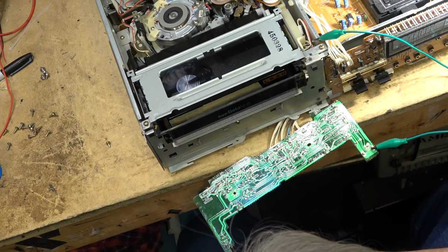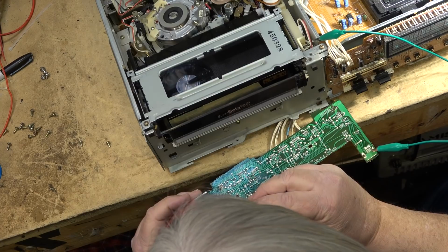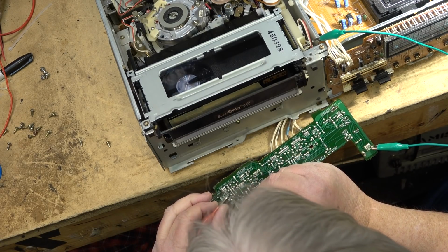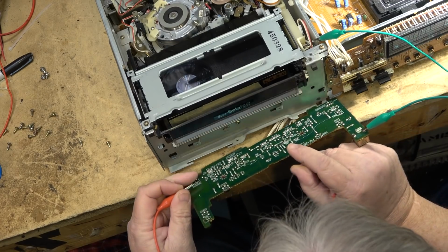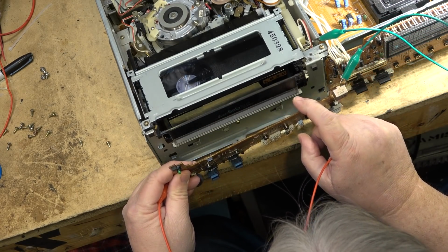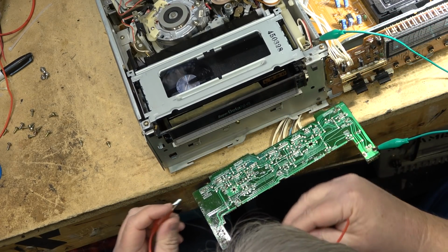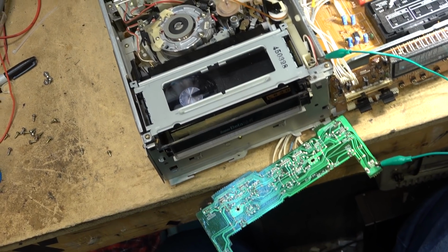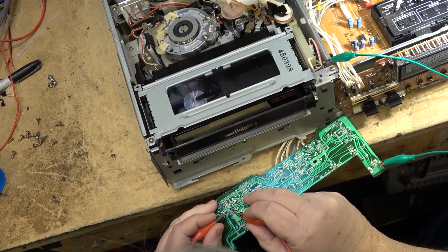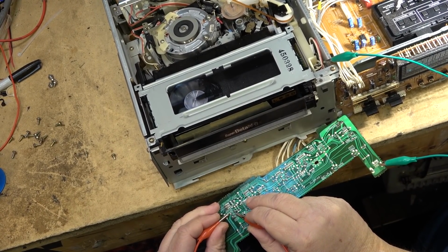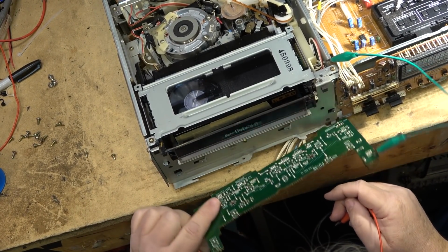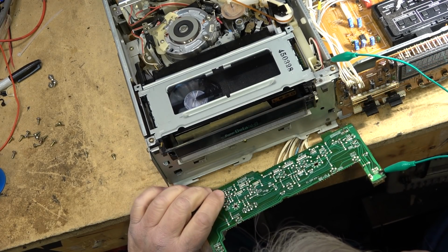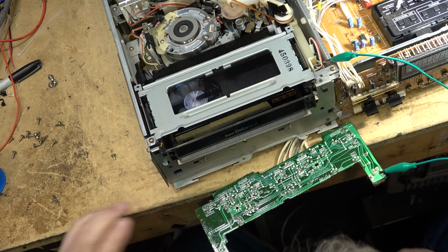But what I'm curious is, is it the switch? Is there resistance being built in the switch? So let's just see. Ah, it's going into rewind now. Stop. If I put my jumper from here to there, rewind. Interesting. I think I might have a bad switch. I press the switch itself, it goes into fast forward.